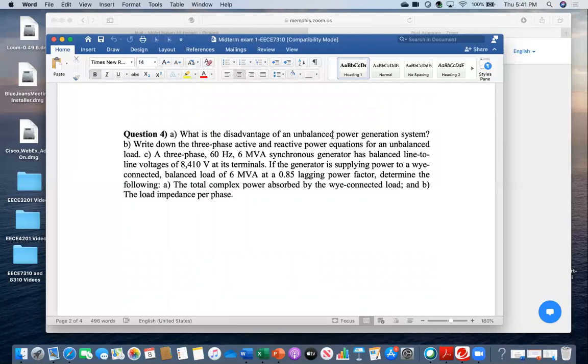So therefore you have to tell that first there will be circulating current flow, because unbalanced means there is voltage difference among phases. Consequently, among phases there will be circulating current that will cause heat, and also zero sequence current will flow through the neutral. So the neutral might be damaged, might be cut, and even it might affect the neighboring neutral system. That is the answer.